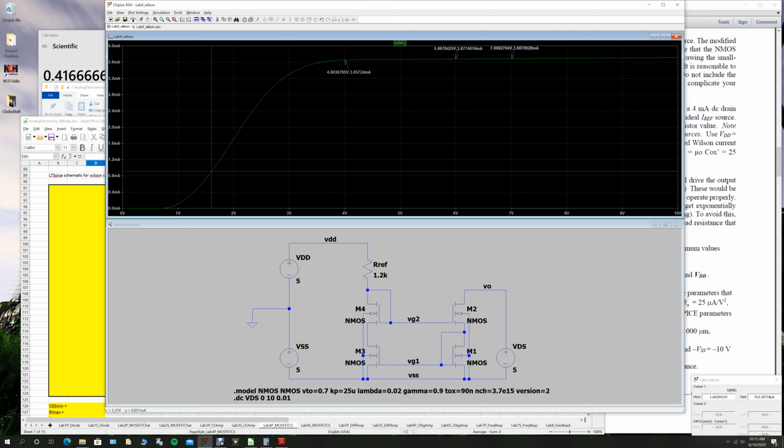Because if this is minus 5 volts, you go up 4, V out is minus 1. So that looks to be about the minimum voltage you can have here. And again, you can figure out what kind of resistance that would be to VDD. VDD is 5, VO is minus 1, so delta V is 6 volts, equal to IR, where the current is about 4 milliamps. You can calculate what that max load resistance is.